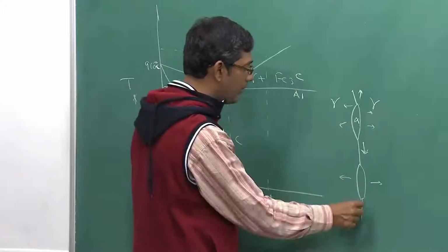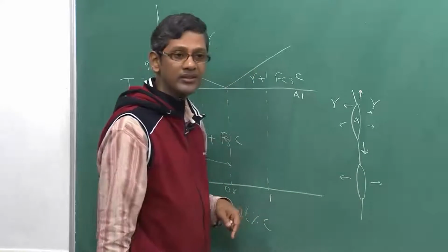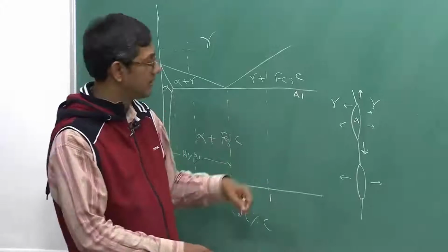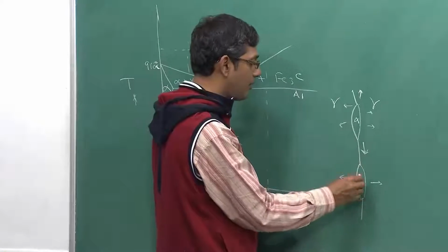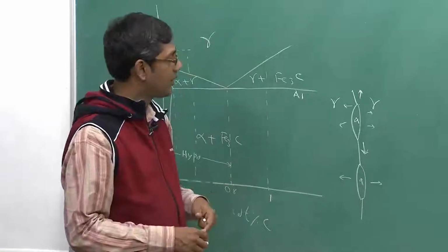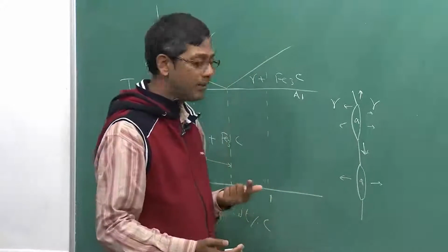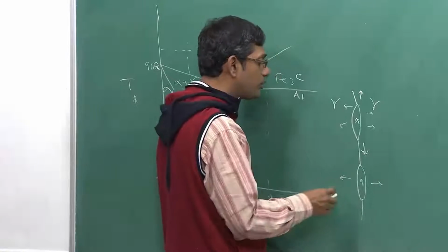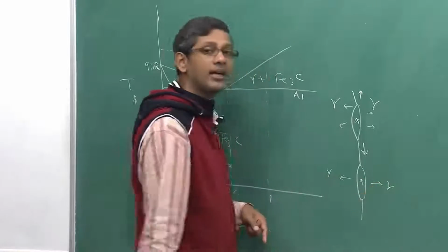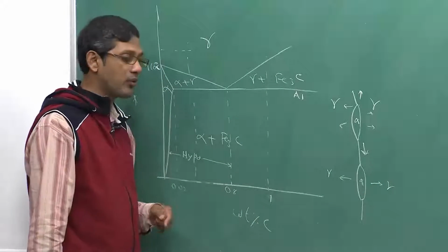Initially they elongate along the grain boundaries because of fast diffusion, and when the diffusion paths of these two neighboring alphas intersect, or have no carbon available, then they move into the two gamma grains. That is why the alpha forms along the grain boundaries.